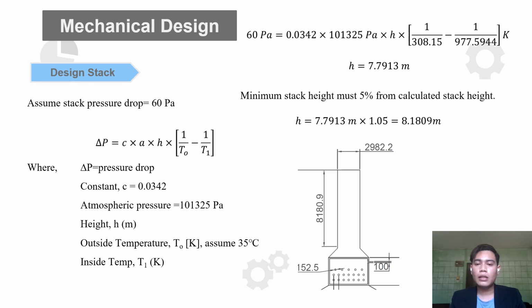So in the PTS as well, Petronas Technical Standard, it mentioned that the minimum stack height must be 5% bigger than the calculated height. This is for the safety precaution. So we have our stack height, which is 8.1809 meter.